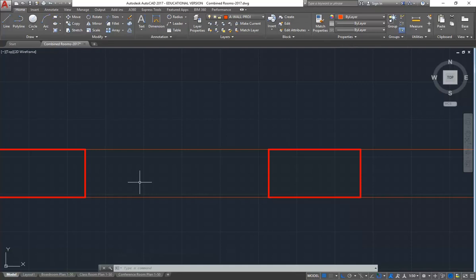I'm not really that worried about the exact size used for the frame, because it's not a construction drawing. The window manufacturers are not going to build the window differently if you draw it differently. They build it in a factory. They know how to make windows. They know more than we do about it. So if you draw your window frame 50 mil and in real life it's 38 mil, they're going to make it 38 mil. So I'm going to say 35 mil is the size, just because it's aluminium, I think, or some sort of metal frame.